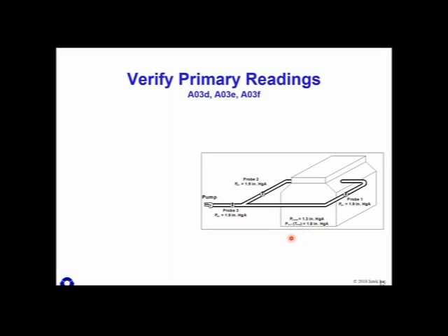Okay. Well, we also have on those plots the condenser hot well temperature, and that hot well has a temperature where its saturation pressure is about 1.8 inches. Now the hot well temperature is not equal to the condenser pressure. It should be right at it. If there's subcooling, then it can be lower. But boy, why is the condenser pressure being measured lower than the hot well saturation pressure? That's impossible. Can't happen on this earth.